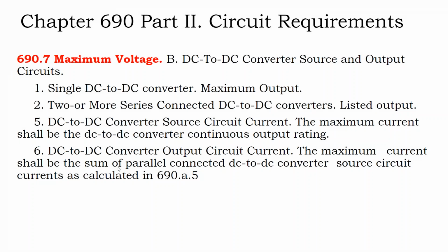With the DC optimizers, you get a little bit more leeway because they are their own forms of voltage control. So you can use the extra length in that circuit. You don't have to have just 10 modules on the circuit, because we can adjust the voltages and increase the amperages and keep the circuit below 600 volts during that time.